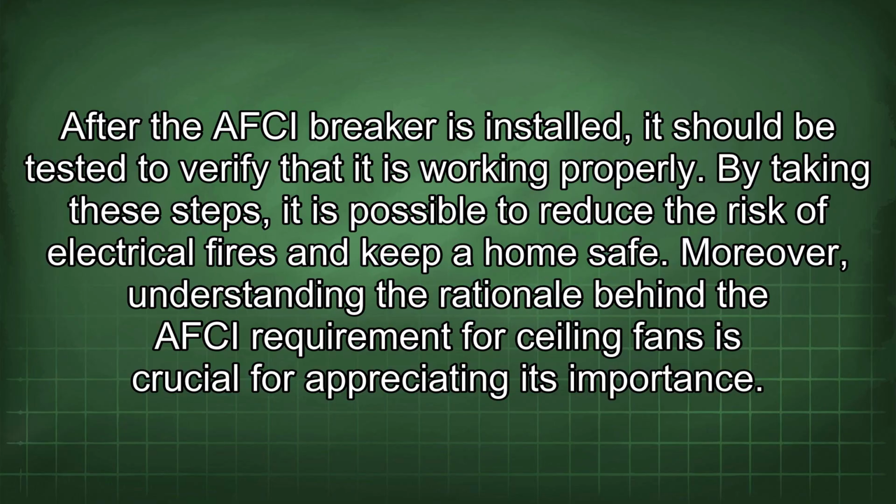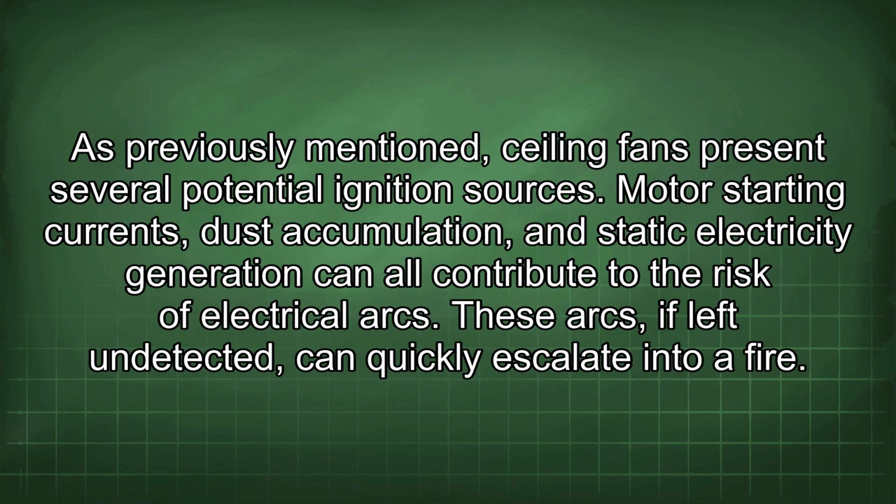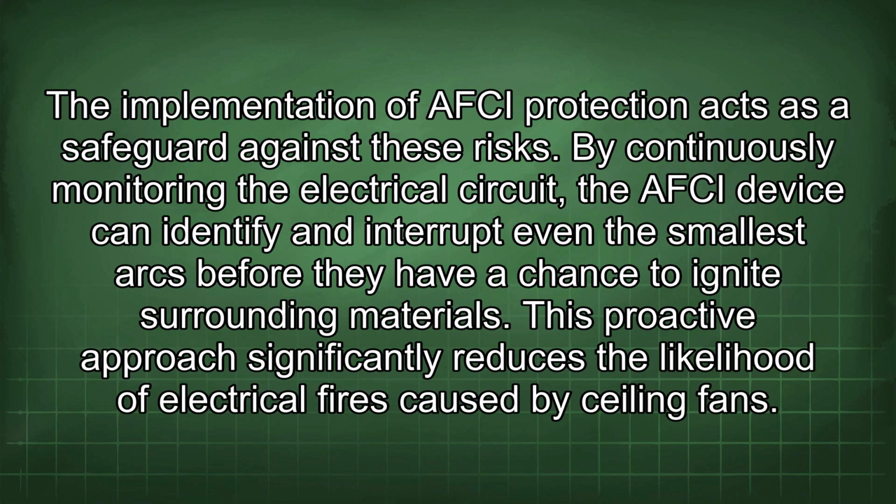Moreover, understanding the rationale behind the AFCI requirement for ceiling fans is crucial for appreciating its importance. As previously mentioned, ceiling fans present several potential ignition sources. Motor starting currents, dust accumulation, and static electricity generation can all contribute to the risk of electrical arcs. These arcs, if left undetected, can quickly escalate into a fire. The implementation of AFCI protection acts as a safeguard against these risks.